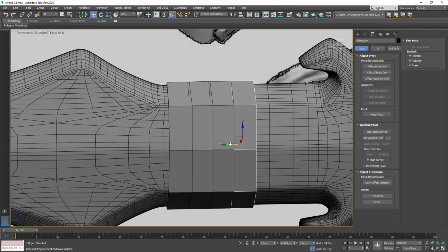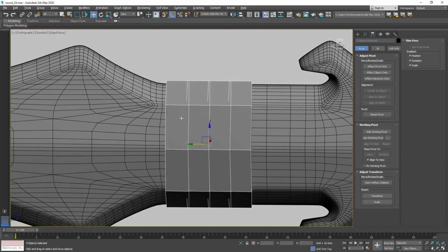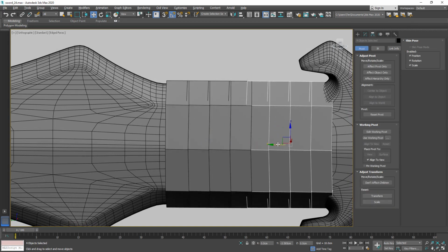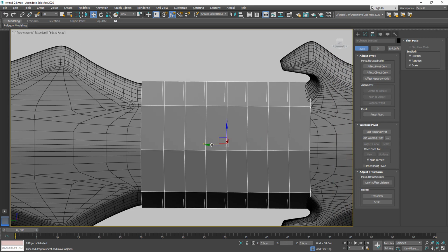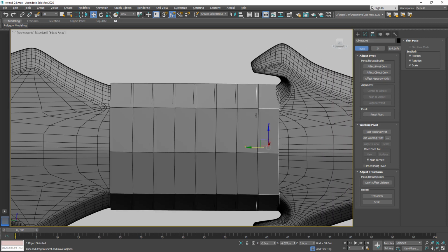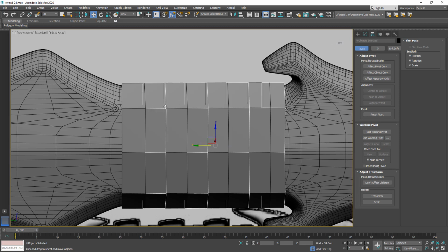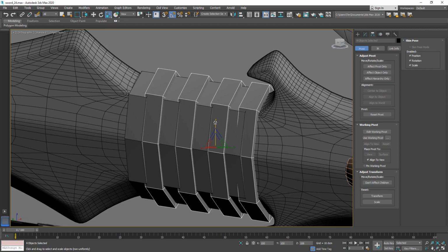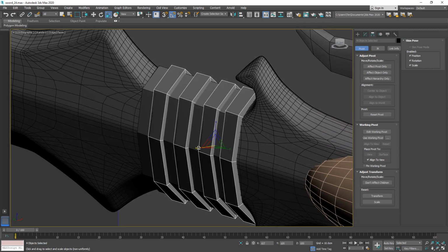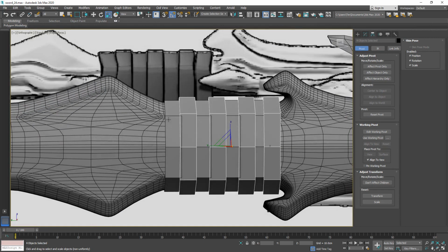So I'm gonna make a bunch of those here. Now what we can do is if we press Control, we have 4 of these guys here. And we can just copy them also as instance. So now we have 8 of these. And let's just push it a bit here to the left. And I'm gonna select every second of them. Go over here to our scale tool and scale it up on the Z-axis and a bit here on the X-axis as well.